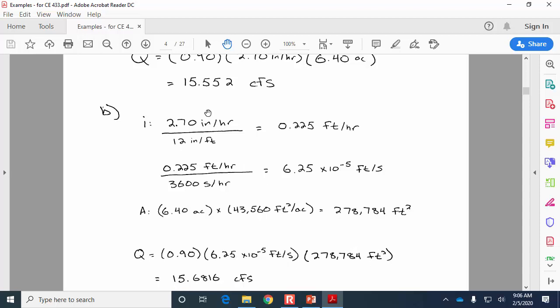Now compare those two numbers, essentially 15.6 CFS and 15.7 CFS. The thinking is that that's close enough together. That's certainly more precise than our ability to characterize the runoff coefficient, the C value. Unless you've calibrated an area and measured the flow rate during a certain rainstorm of a known intensity, which is a way you could back-calculate the C value, if all we're doing is looking it up out of a table, our capability of accurately estimating what C value should be used is way worse than how closely this agrees.